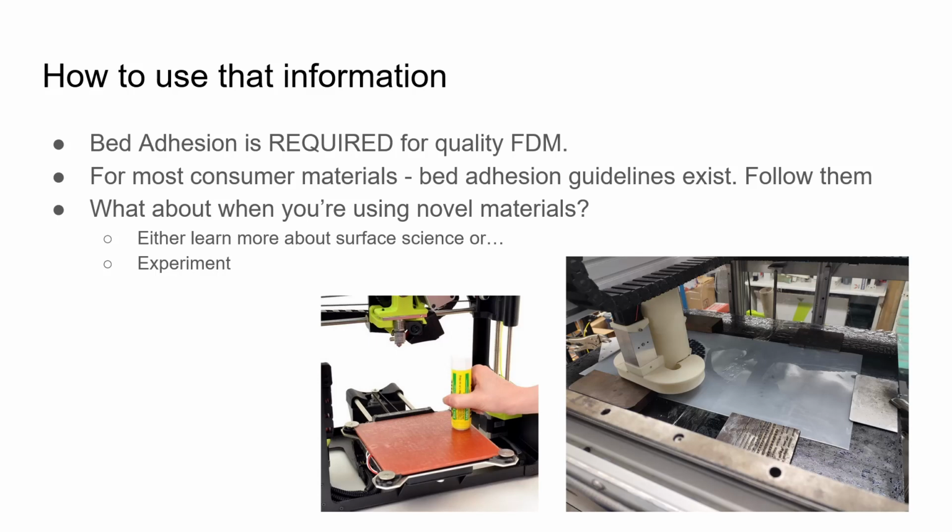And I found worst case scenario, right? Worst case scenario, if you need to get your print to start validating some results, something that your material will always stick to is itself. And so my solution when I really wanted to get up and rocking and rolling to start getting some preliminary results was I just put down a sheet of low density polyethylene to print on top of, and it worked. Obviously it fuses together really well, but yeah, that's what I needed to get myself rocking and rolling.